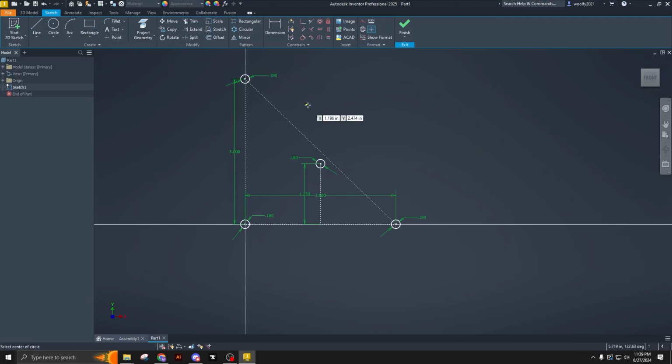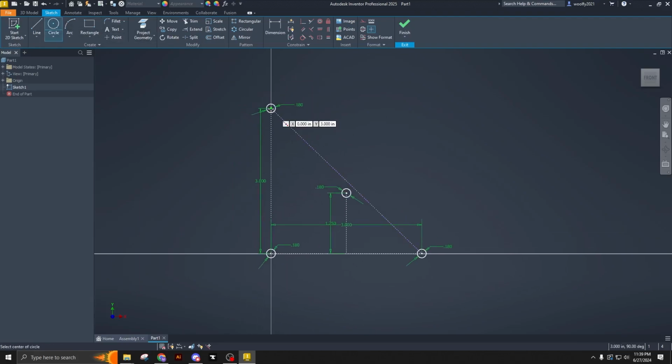So I suggest coming up with some sort of minimum size or minimum amount of plastic you want on the outside of a hole before it can break, depending on whether you're using polycarb or Delrin. We normally work with about 0.4, 0.5. I'm just going to do 0.5 for this tutorial. And we're even going to come into this hole on the inside of this triangle here and just do .5, just to make sure that we're all within the area that we want to be in.